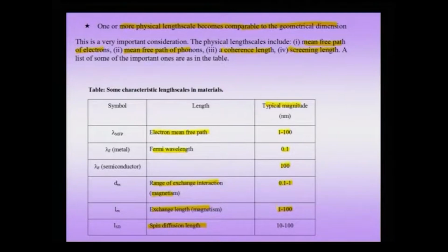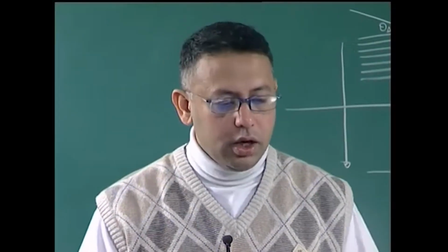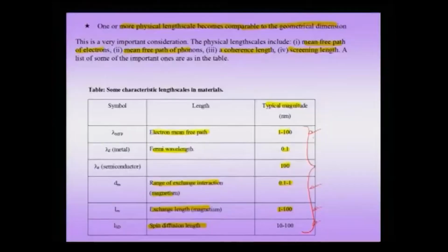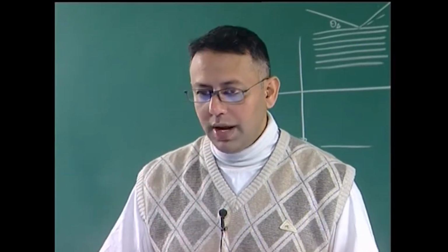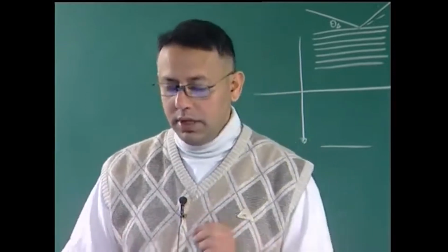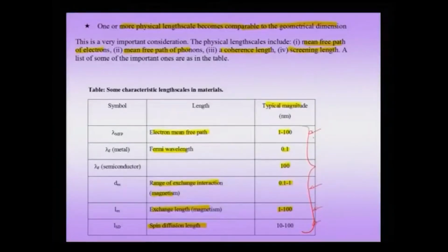So, when my particle or crystallite size starts to approach any of these dimensions, and of course, if I am talking about a magnetic material, I would worry about some of these effects. When I am talking about conductivity, I would worry about the electron mean free path. Then I would see that my properties are going to drastically change when I go to the nanoscale. At the heart are more profound effects, because I am not merely saying the material is becoming smaller, and it is not a gradual effect that is going to change, but it is going to drastically change when I hit these magical numbers or physical quantities, below which my length scale is going to lead to a drastic change in properties.